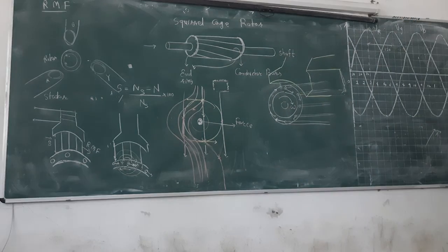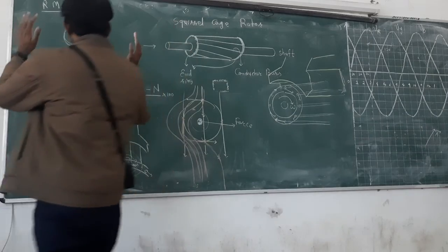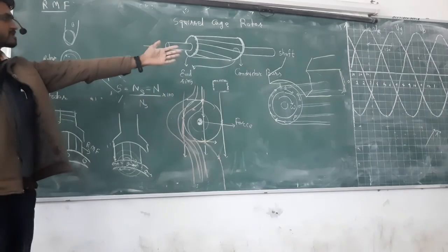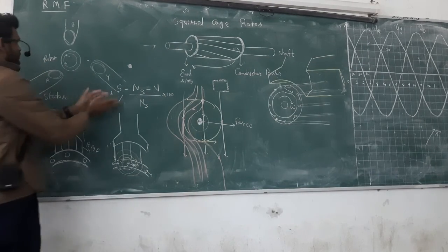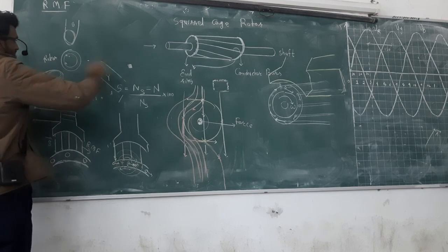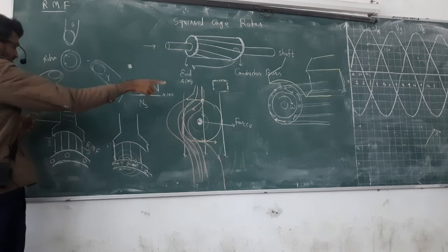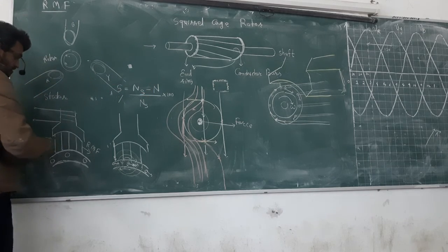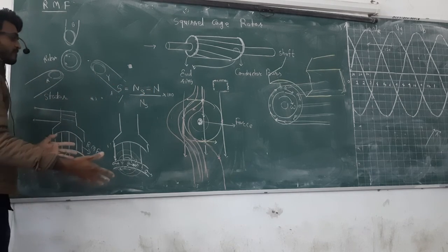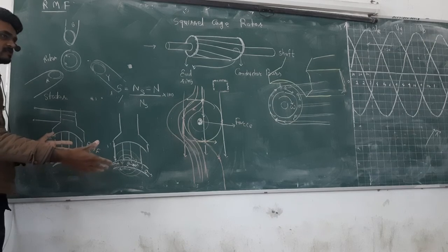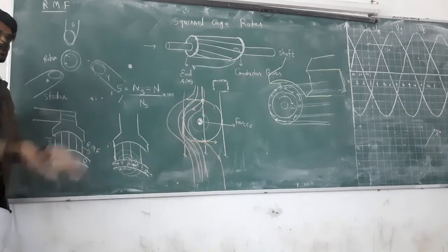But the key thing is that you have to clear this idea of the motor. How is the rotating magnetic field created? Because of the supply we give here, and all those vector additions, the rotating magnetic field is there. Now there is a rotor, there is a conductor, and with the rotating magnetic field we have to use Faraday's law of electromagnetic induction.